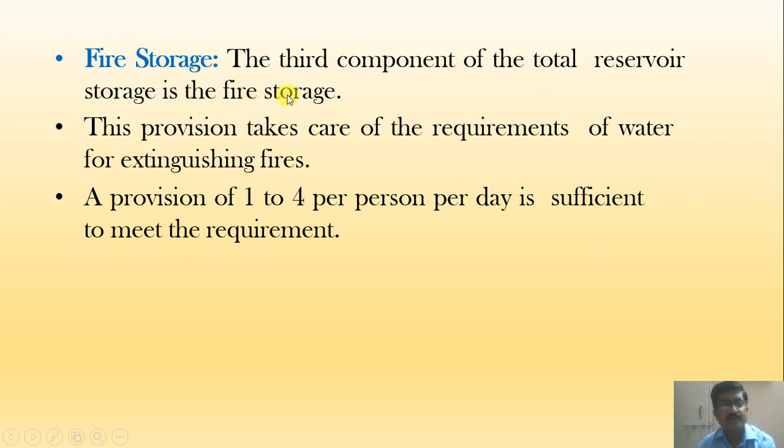Fire storage, the third component of the total reservoir storage. This also we have discussed. This provision takes care of the requirement of water for extinguishing fires. Here a provision of 1 to 4% of the per person per day supply is sufficient to meet the requirement.